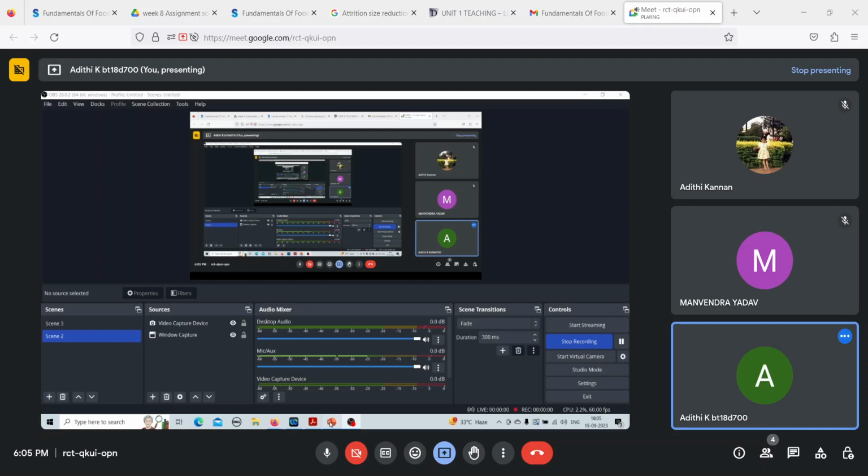Let's say, for an example, we want the number length diameter, which means p will be equal to 0 and q will be equal to 1. When you substitute p and q in the formula here, you will get summation of d into n divided by summation of d power 0, which is 1, into n. So automatically this will give you the number length diameter formula. You don't have to memorize as long as you know this particular equation and what is being asked.